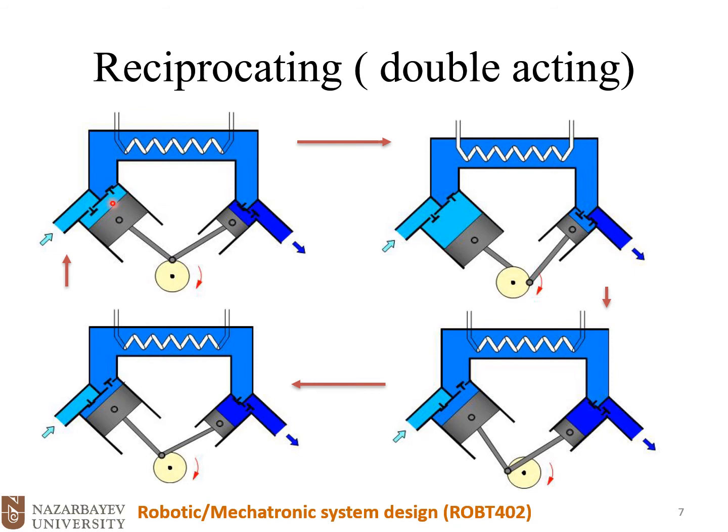Of course, these valves basically go through an order of opening and closing. For example, in the sucking stage, the first one is open and the second one is closed. For the compressing stage, both of them should be closed to a certain degree, and then the second one should become open to exhaust the air. So now we have a higher pressure air.